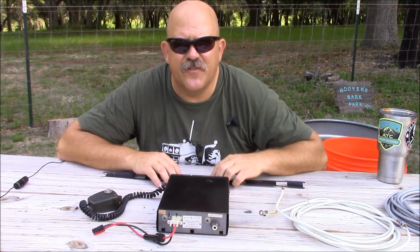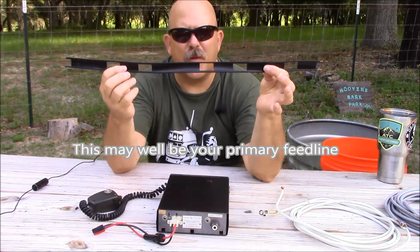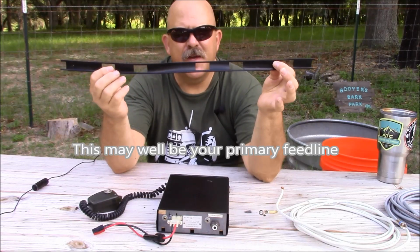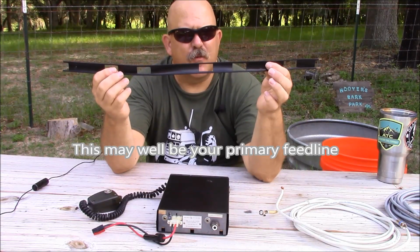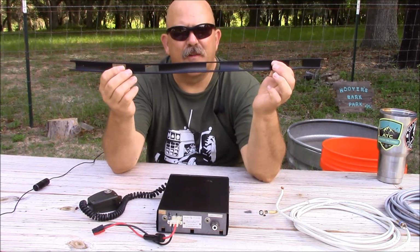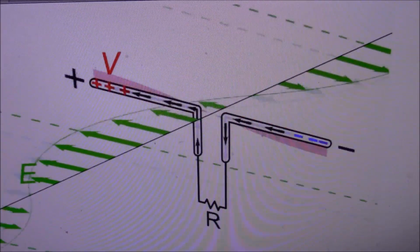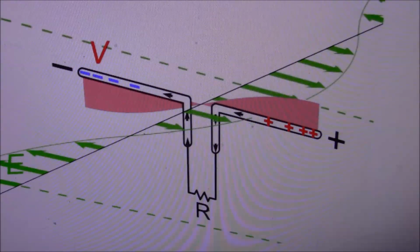Now, our contingency type of feeder is going to be something like this, and this may be your primary depending upon your radio setup, and this is just balanced feed line. Now, we call this balanced feed line, of course, because there is typically no relationship with ground in the employment of this feed line as designed. Our parallel feeder is considered to be a balanced feed line.